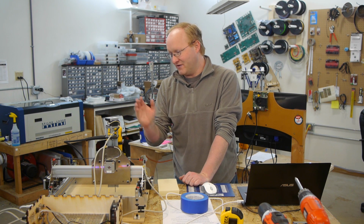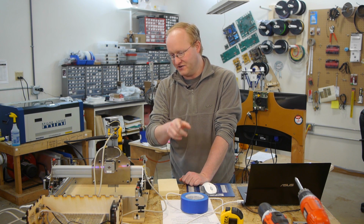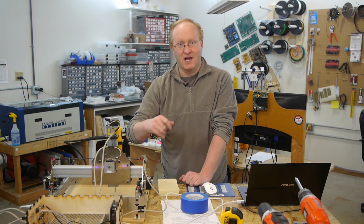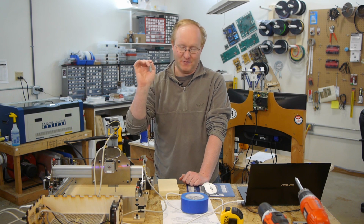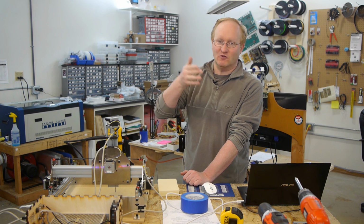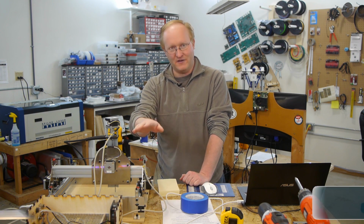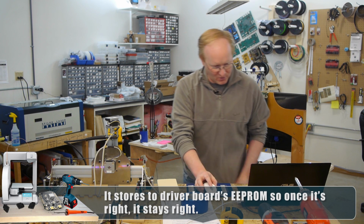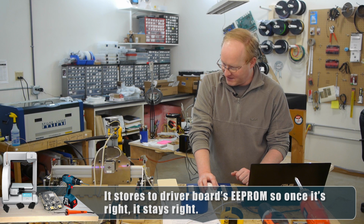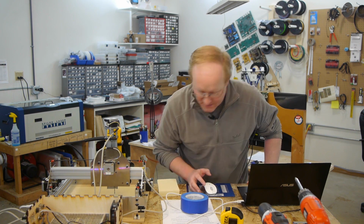So it's a combination of your motor steps, the micro stepping that your board is set to, and your pulleys and your toothed gears. Because you have to think that the pulley's diameter times pi will tell you how far it will move with one revolution. So you have to put all that stuff in. I've already dialed that into this one, so it should be pretty good. The one thing I do want to do is set a 0 point. And I'm actually going to put the material in first before we do that. So I'm going to move the machine.